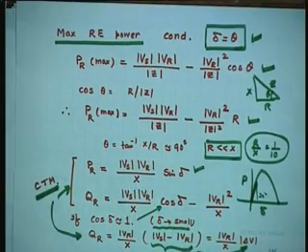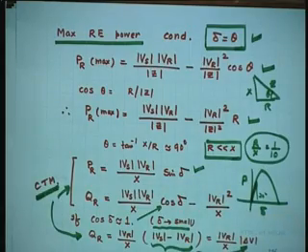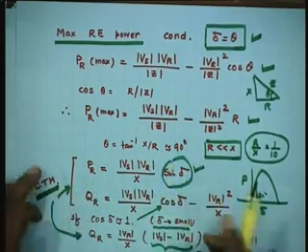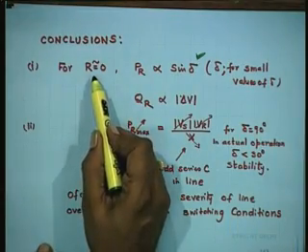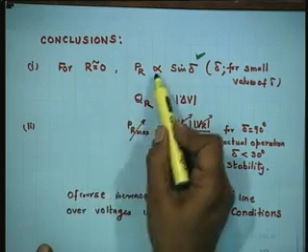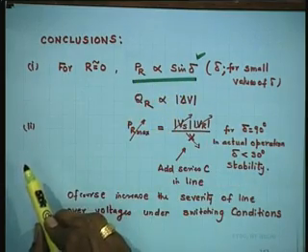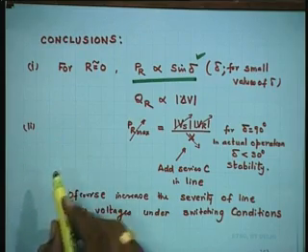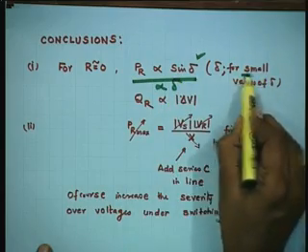Once the line is built, x is known, and Vr and Vs are roughly the same, fixed. So, the only variable is sin delta. That is what I am writing here, that when R is low or 0, PR is directly proportional to sin delta. And if some more fellow is interested in getting further simplification, this becomes proportional to delta itself for small delta,